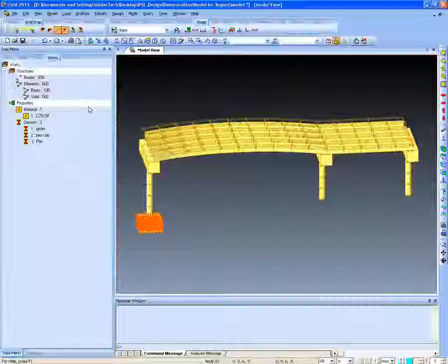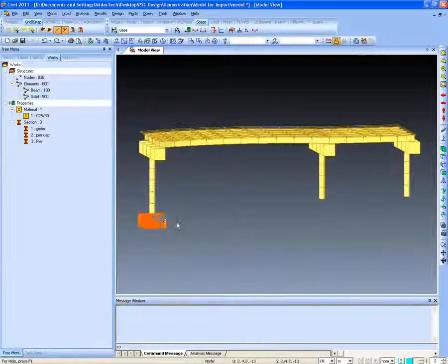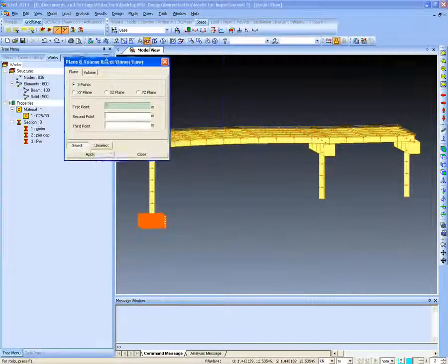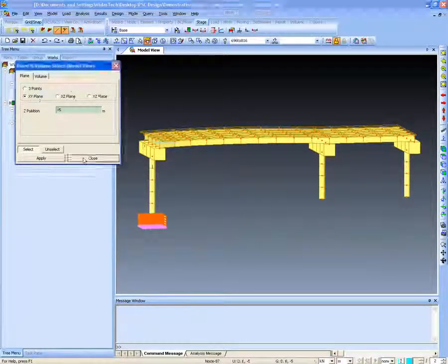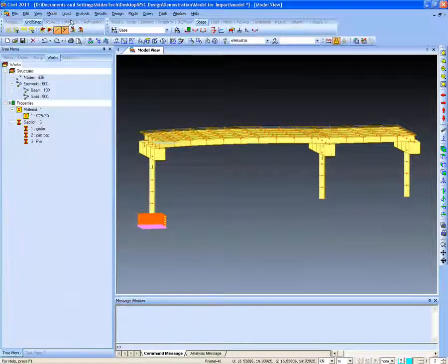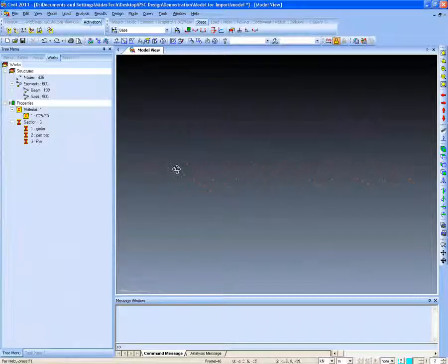to let you know how we can apply that. For using the point spring support, I will generate the piles at the base of this footing. For that, I will select the nodes. I will activate the nodes. After activating the nodes, only the nodes can be seen in the entire model.